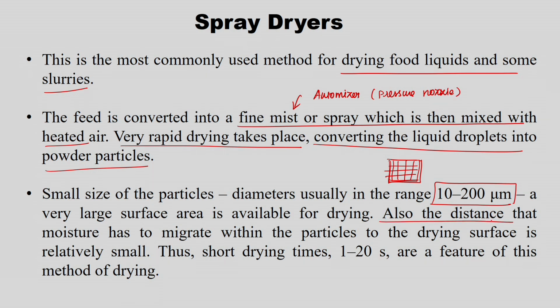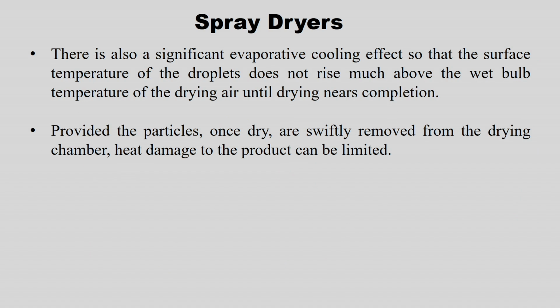Also the distance that moisture has to migrate within the particle to the drying surface is relatively small. So think of a food material, from this point to this point, the moisture has to migrate. If I have a very small particle, this height is also reduced, and in that way you will have less drying time, which is about 1 to 20 seconds.